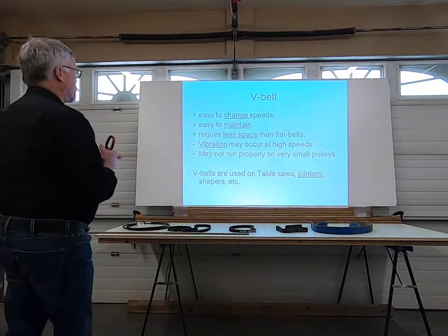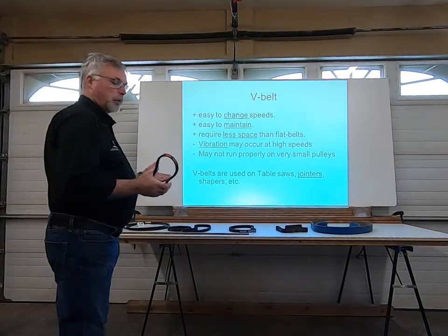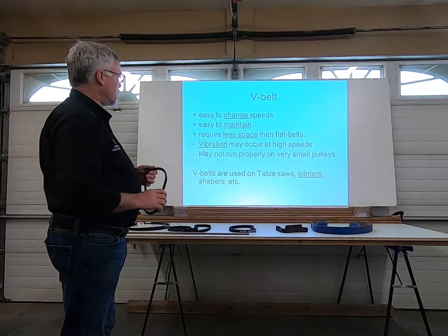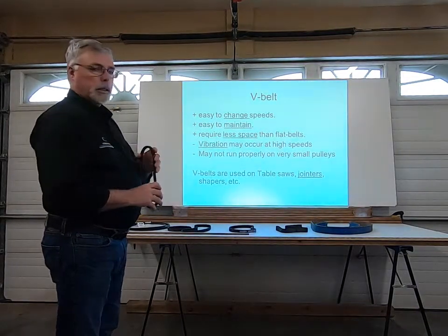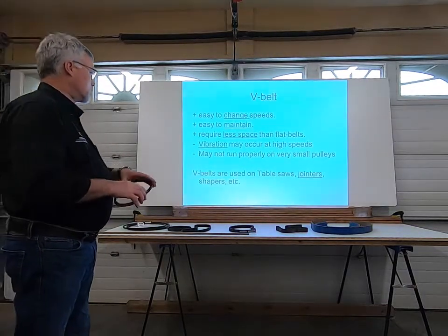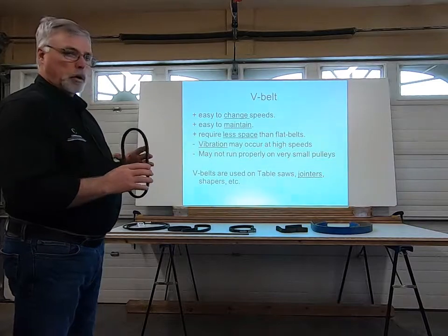So belts are easy to change. They're easy to change speeds. Simply by changing the size of the pulley, you're changing the speed. They're relatively easy to maintain. They require less space than a flat belt. Vibration may occur at high speeds. It may not run properly on a very small pulley.